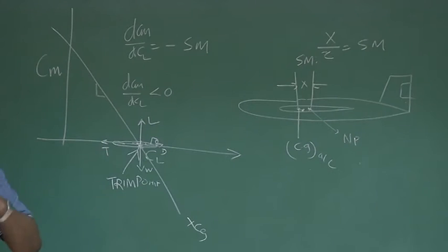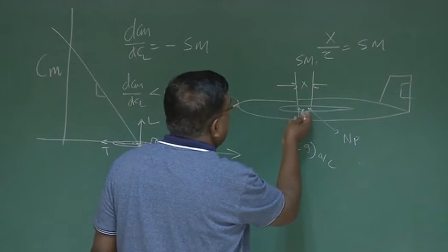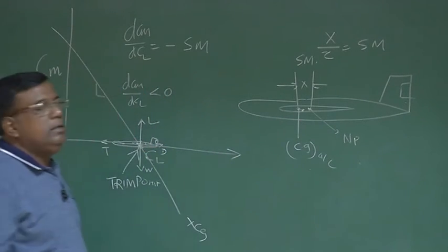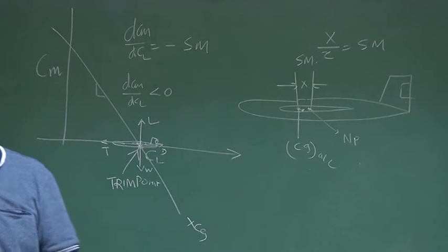It will become more flatter, and also physically you understand if the separation reduces, so there is a reduction in the static stability. And at a point, very clearly when CG coincides with the neutral point, it is neutrally stable. So there is no restoring moment. Okay, this is, we understand.